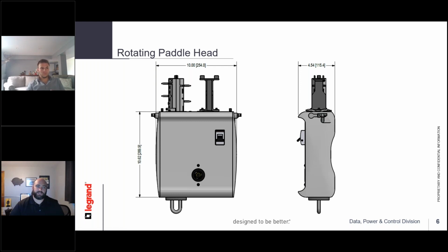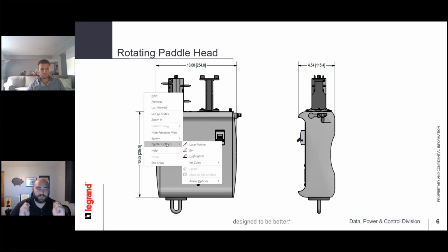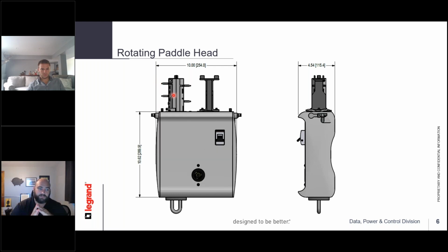So what you would do is install the plug with the paddle head running parallel to the busway, flip up both claws on each end, then either from the floor or from below, you would pull and rotate the lower lever at the bottom, and that would engage the contacts into the busway. So what's actually rotating here, Corey, is this piece here, this bus plug.